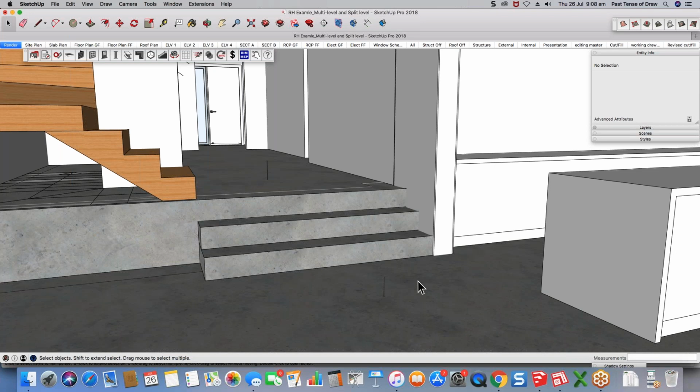We're going to quickly go through and discuss how you model it and the different kinds of scenarios, as we said earlier. But we're also going to show you how you can make sure that you keep track of the heights. At the moment, it isn't automated. So when you put in a floor, it doesn't have an RL or a finished floor level or anything associated to it. It is a manual requirement that you keep track of that.